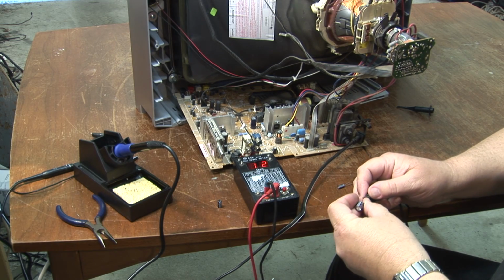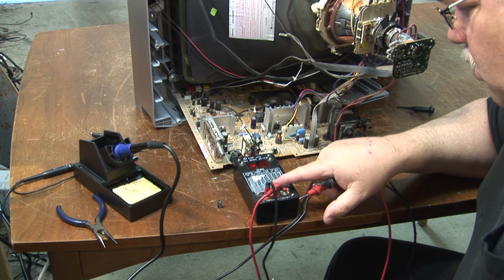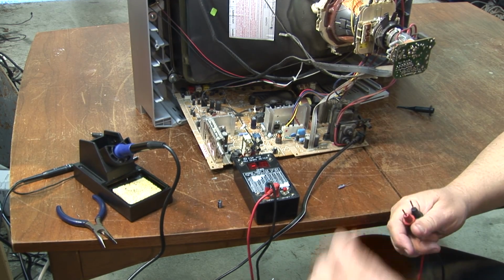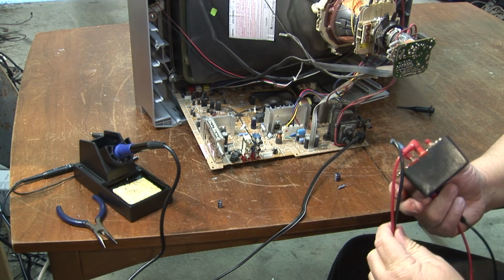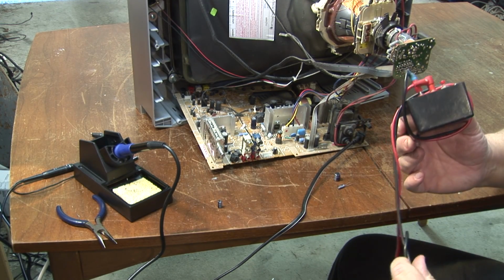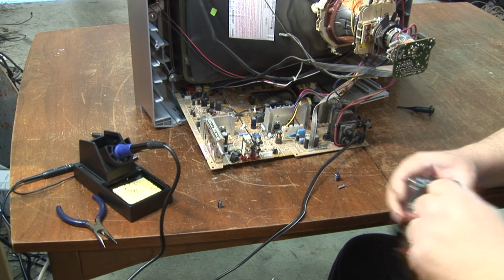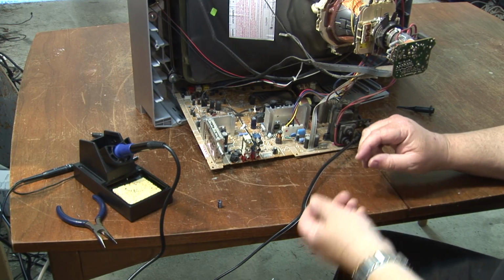Here's a 100.2, and a 100 says it should be no worse than 0.32. So we're at 0.2. So there's our new capacitors here. Gone a little bit up in the voltage on them. I went to a 50 volt because I didn't have a 35, so a 50 will be more than enough headroom here. Let's get these new components mounted on the board here.